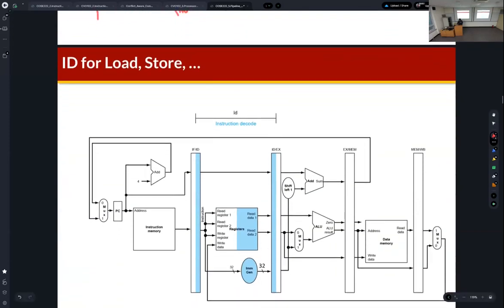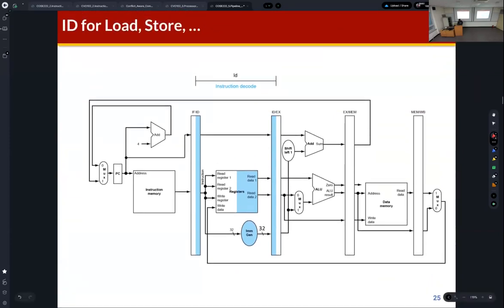And then the next clock, this is the ID stage. Also, we can find some clock signal here. So the sampled PC and sampled instruction are delivered to the ID stage at this timing, just at the rising edge of clock.